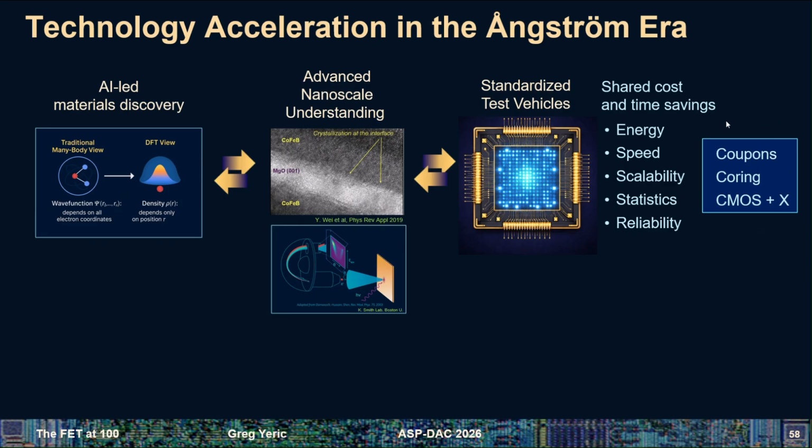I was working on this, had this pretty much done in my last job where we would have say Intel and Micron have access to EUV tools, would create test chips or test structures at the nanometer scale, and then dice them up, cut the wafers up into pieces that the university researchers could deposit their films on, and then when they got data, they knew it was coming from nanometer features that they could never print in their own lab. And you can also do something called coring.